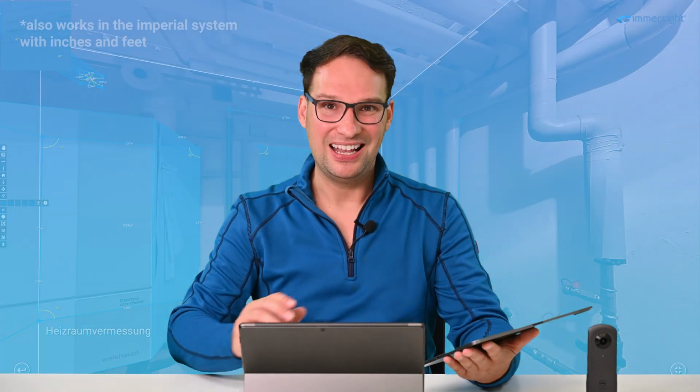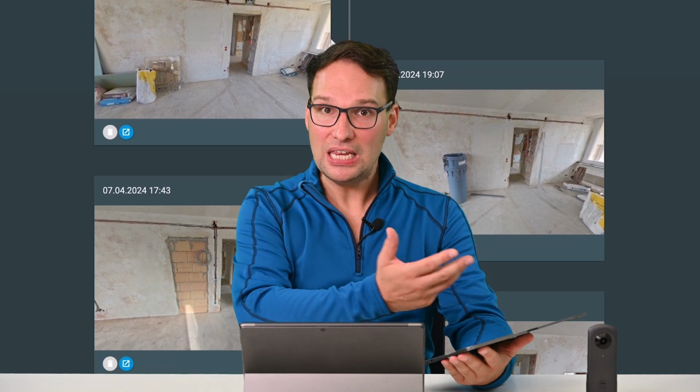And now we are coming to the big question. What do you want to do with that technology? What do you need? When you need a measurement system and you want to make measurements to the millimeter, then you need a laser, not a 360-degree camera, not a LiDAR iPad. You need a laser. But when you need a system that can make measurements with 99% accuracy, within some centimeters, then you can rely on a 360-degree camera. LiDAR is a little bit problematic. When you need documentation, for example from a construction site, then you need a 360-degree photo to see what's going on at the job site. The LiDAR technology is not documentation. So it's up to you what you need. I can just recommend 360-degree cameras because you have the traceability to see and work with it.